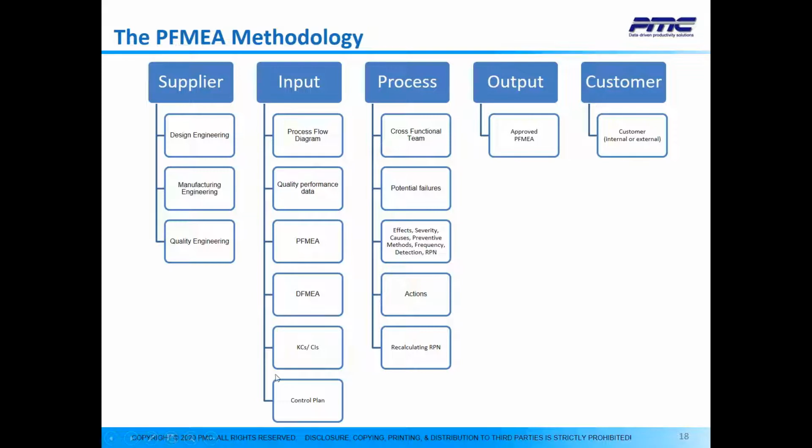Now, again, these are the input for a PFMEA, but of course, the PFMEA for a similar part or the same part or component for the legacy program can be used as an input to develop the current PFMEA. Same thing again. Anything in the input here is either the initial, first draft of the documents or the risk assessment, or where you can bring the similar parts, product families, PFMEAs and DFMEAs, and again, use those as an input to develop the PFMEA.